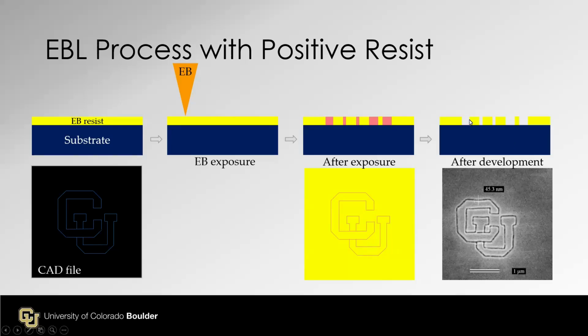After development, the exposed area is removed. In the positive resist process, the exposed area will be gone. In the negative resist process, the exposed area will stay.